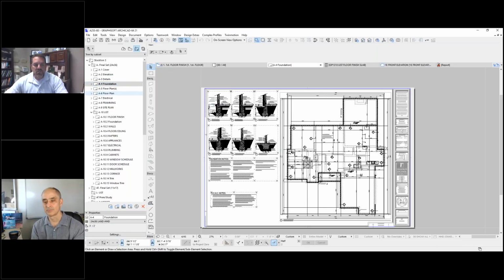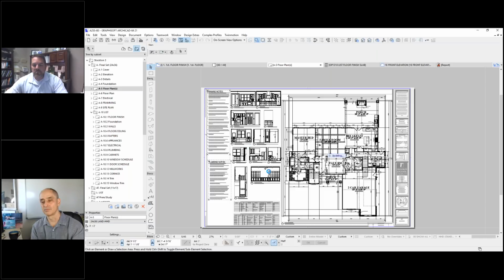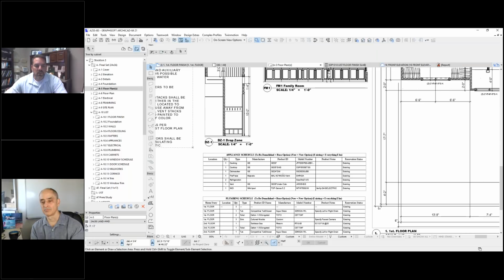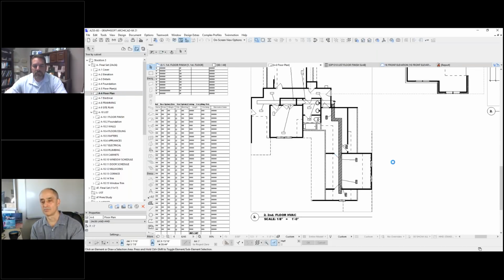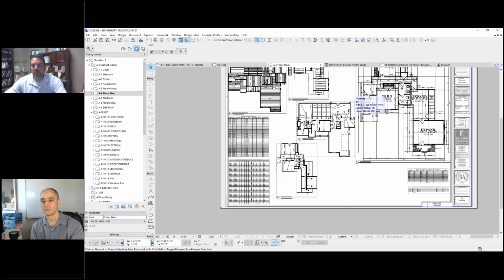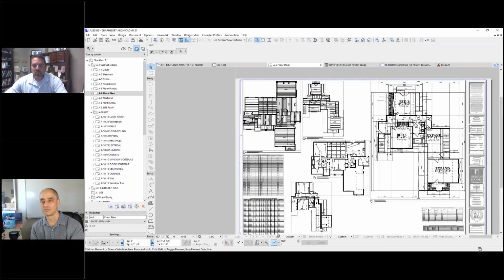But we'll do our foundation sheets, and then floor plans with interior elevations, and then of course we use typical schedules as far as your counts for your plumbing and appliances. And then we'll do a duct layout, which in this case is two stories, so a lot of it is in between the floors. So we had to coordinate with the floor joist manufacturer and make sure that we coordinated where our spans were and what direction they were heading, so that we didn't run into any snags with putting beams in wrong locations and stopping our duct work from where they needed to go.